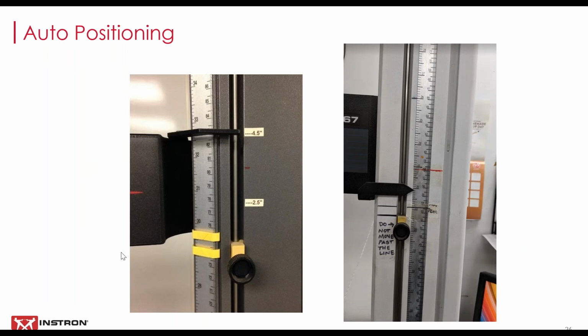Even when sharing test methods, using different fixtures or setting the test frames up incorrectly can cause differences in data, especially in labs where load strings are changed around often. There's really a risk that a user might install different fixtures for a particular test than was previously used.